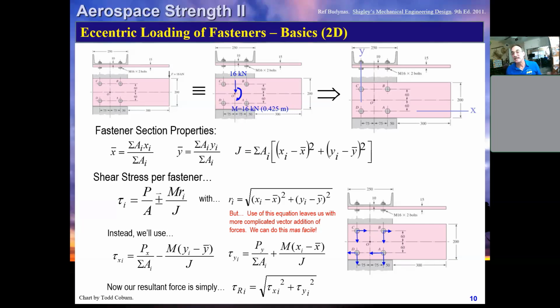Now this is the stress, which we can use to evaluate the strength, or we can get the force in the fastener by simply multiplying the stress by the area of the fastener, okay? And these are our little resultants. Watch the little graphic as we replace each of these pairs of perpendicular stresses by their resultant stress. That's what we calculated using these equations. This is the easy way to do shear analysis of fasteners, or the analysis of eccentric fastener patterns.